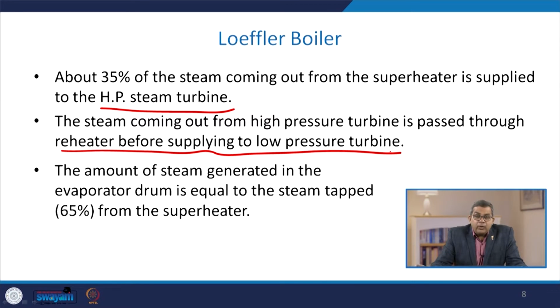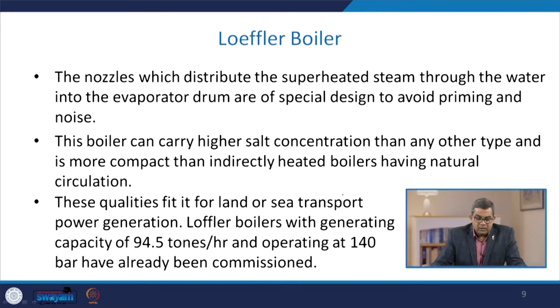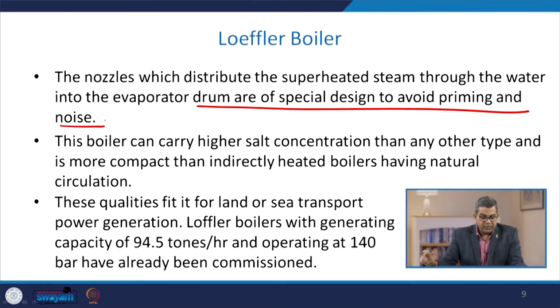So the amount of steam generated in the evaporator drum is equal to the steam tapped, that is 65% from the superheater. Now the nozzles which distribute the superheated steam through the water into the evaporator drum are of special design to avoid priming and noise.